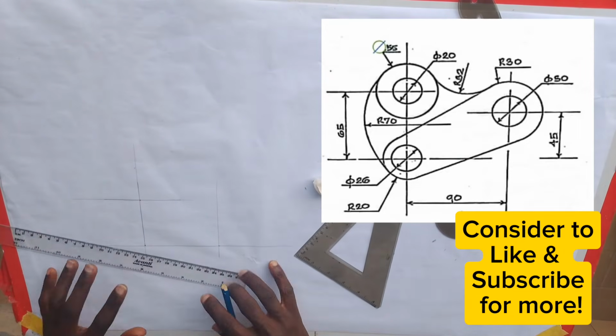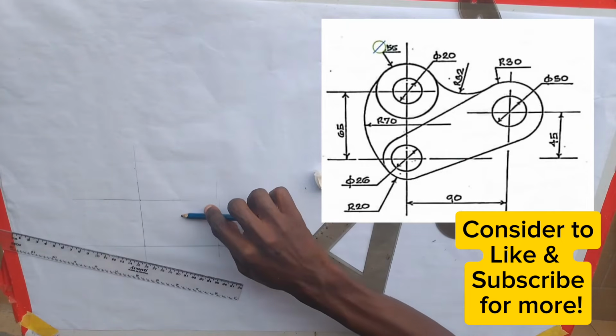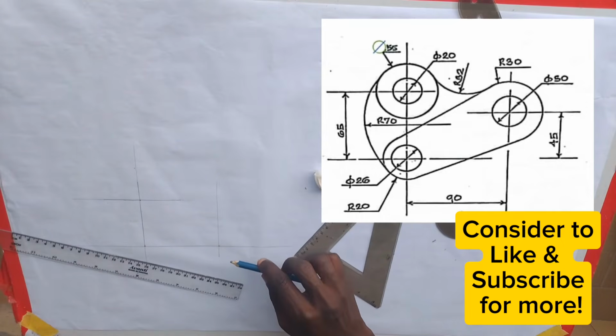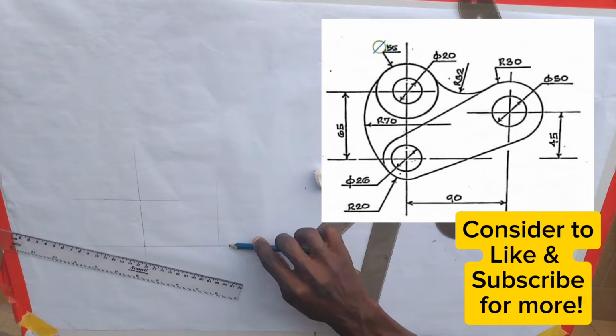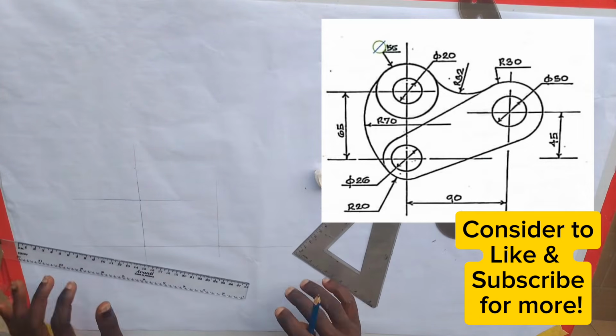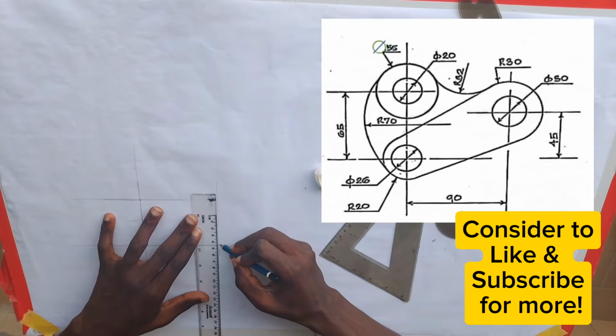Now, this for this aspect. You now see that from here along this line, there's a line that comes like this too. So we need to draw the line. But for us to get the line, you need to know the distance from here to the line. And the distance from here to that line is given here to be 45 millimeter, and that is 4.5 centimeter. So I'll measure 4.5 here.